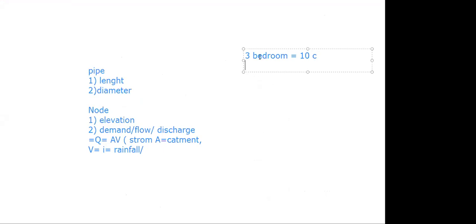And we're assuming the standard specific water demand per person, let's assume 100 liters per capita per day. In other words, each person should not use more than 100 liters per day. And we say we have our peak factor to be, for ease of calculation, let's use 2.0. It's between 1.3 to 2.3.